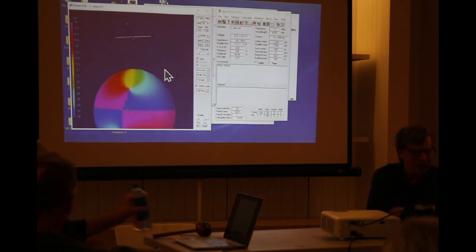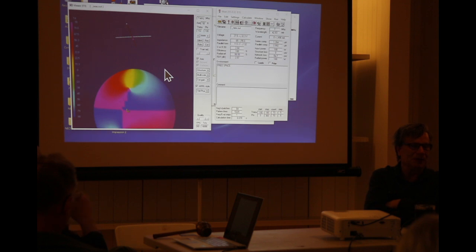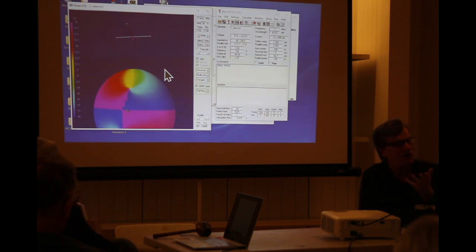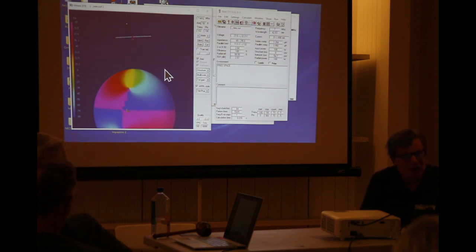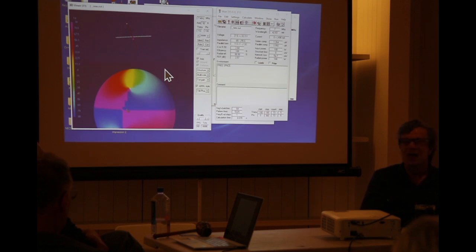At HF, it's noticeable. Not so much the axial ratio, but between clockwise and counterclockwise, on a single hop, it could be 3 S units difference between being matched polarization and unmatched. Jim Movius and I did a lot of experiments, so that was just pretty dramatic. Another thing that is very interesting, when you're listening to auroral noise, is circularly polarized. You can see a big difference between X and O propagation.